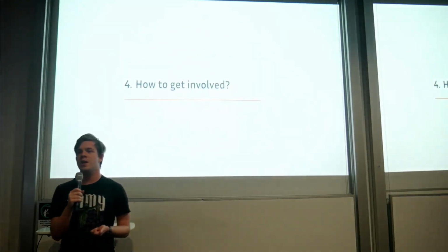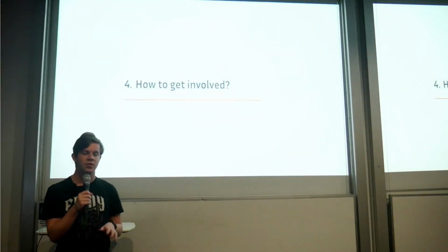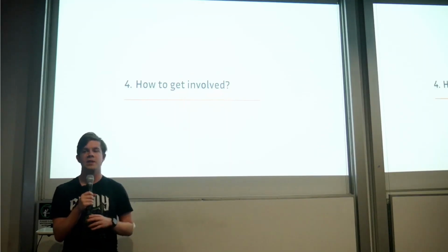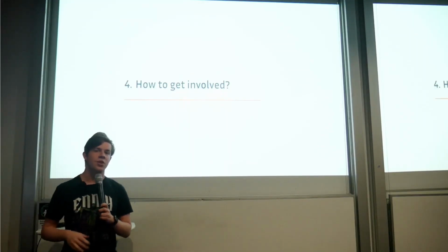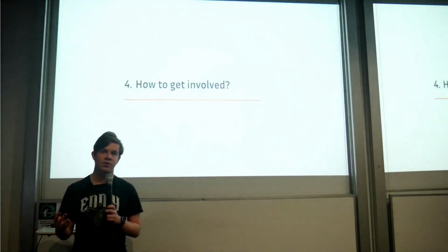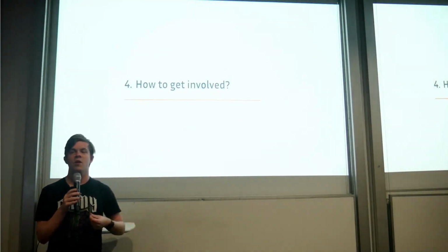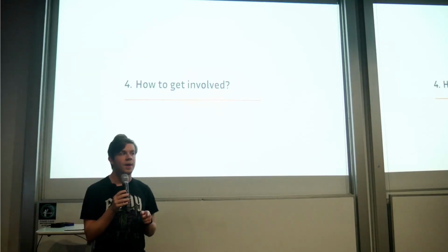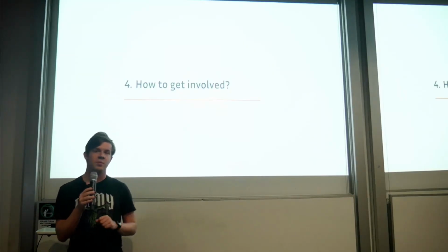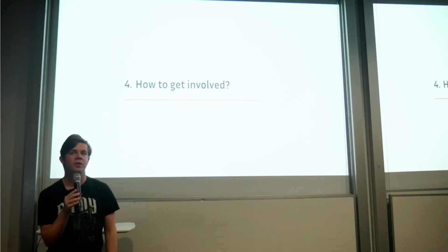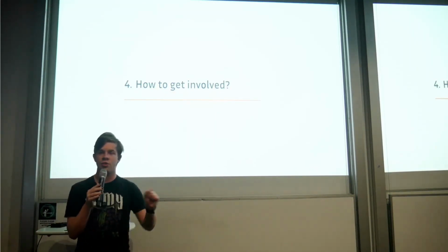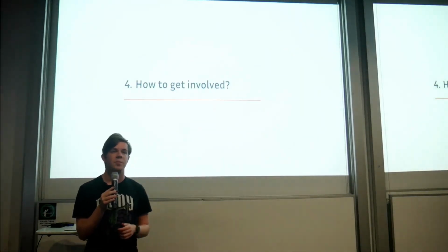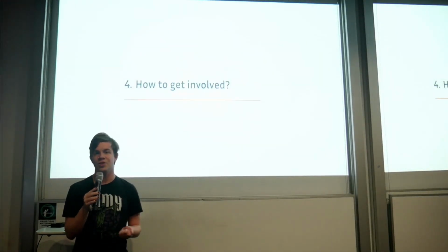A lot of the time that you spend in the design pipeline is going to be tweaking design parameters to meet what's called timing closure. You want your chip to run at 1 gigahertz, so you have to make sure that you can actually run it safely and assuredly at that. Also, I skimmed over it a little bit, but of course the antenna analysis is very important, because these long traces on your ASIC can actually turn into antennas and pick up background noise, and it's not good. So yeah.